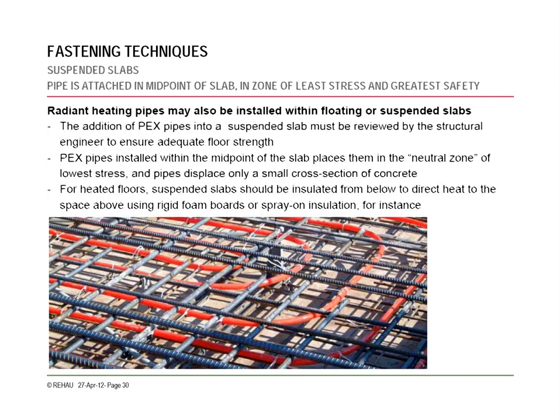This is just a quick note on suspended slabs. This usually happens in commercial junctures, but if you're going to be pouring a floating or suspended slab, no problem with the PEX. The structural engineers are going to have a say in it, and a lot of times they'll question how much pipe you're running through there, and just need to know exactly what's going on. But the pipe makes up such a small cross section of the concrete that you're really not disrupting much.